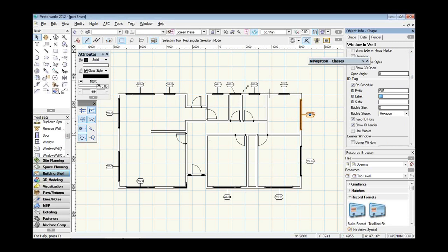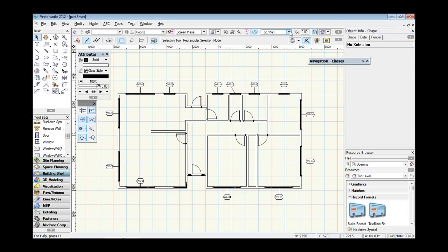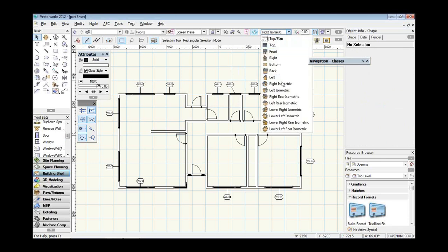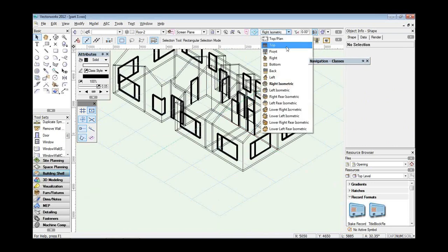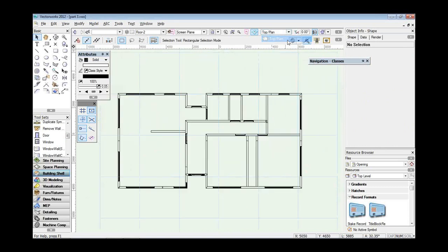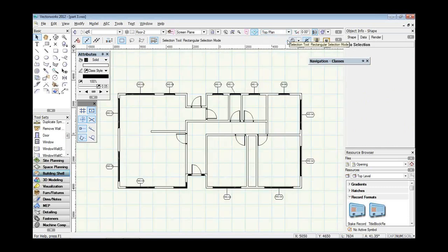So we're building a 3D model. Let's look at this in an isometric view. I've used my fit walls to roof, so you can see I've extended my walls up to meet the roof. Once I've created this information, I've got my building and I've got the plan view, I could then use this to create drawings. So I could create something called viewports and sheet layers to create my drawings.